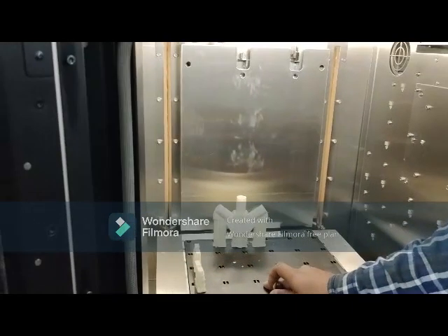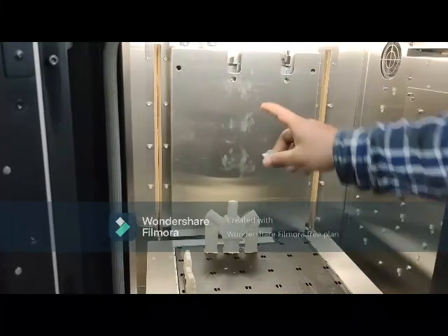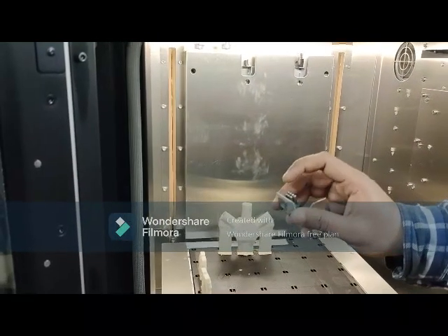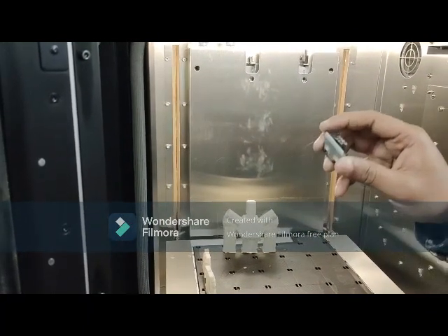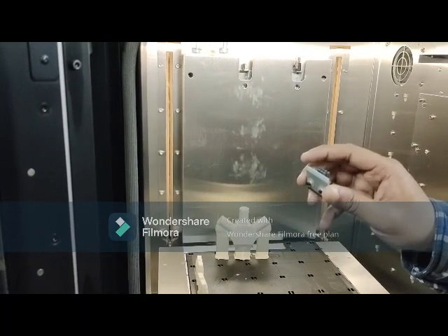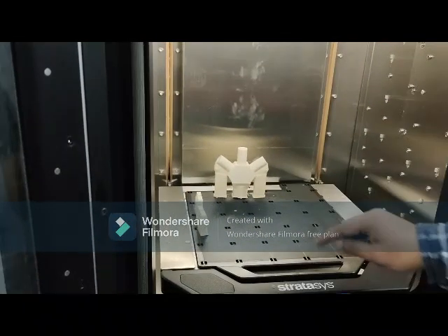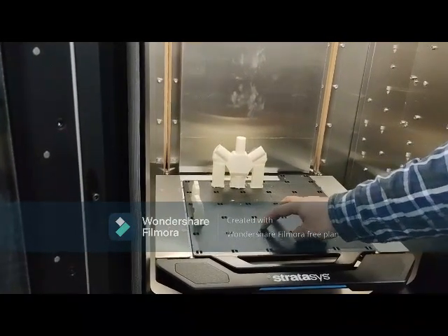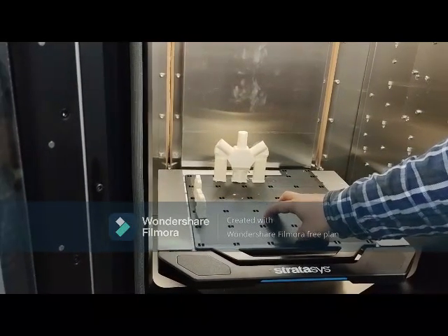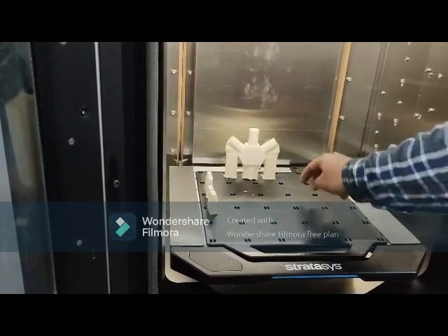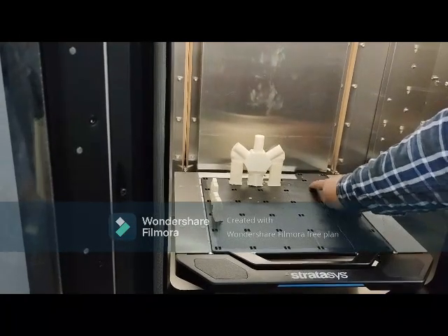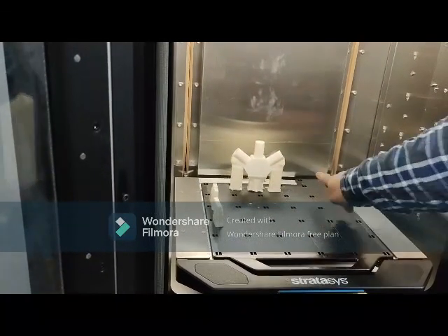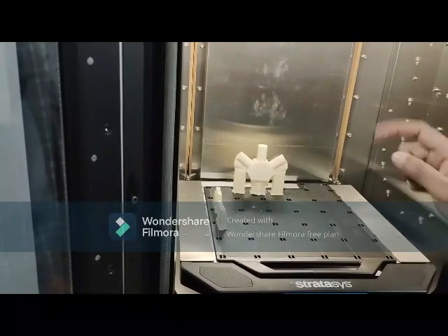After printing a single part, each and every time it will move to this portion, that is the backside portion. In the flip and the brush, it will try to clean the nozzle head. After cleaning the nozzle head, it will come to this section where the purge tower is kept, and here it will try to print one more layer, same layer, the layer of this geometry. Suppose we are printing something here, and we have a circular disc here, and we are printing something of the first layer. After the completion of first layer, it will go somewhere in this section, and it will try to build the purge tower. The height of this one and that one will be same for the first cycle.